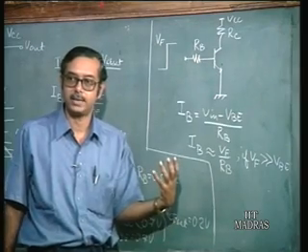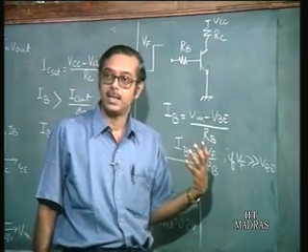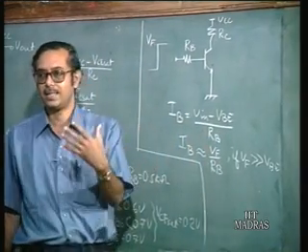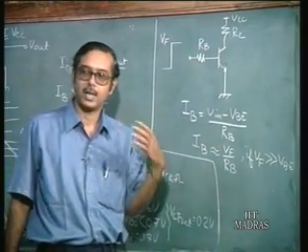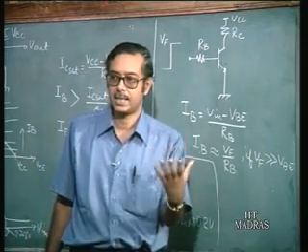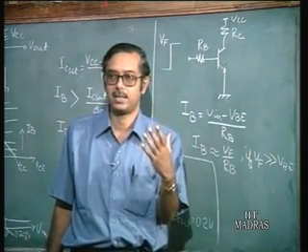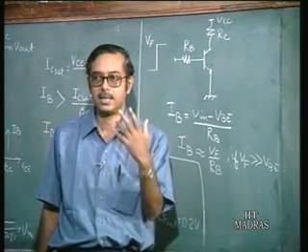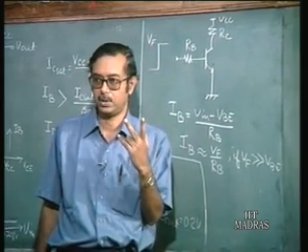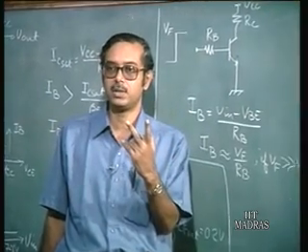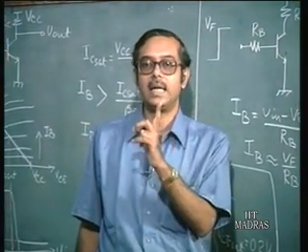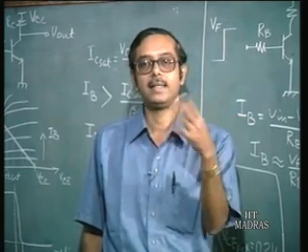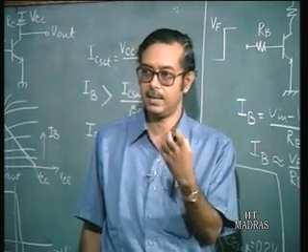So, the relation again is, for that, let us consider a transistor. Let us go back a little bit. We have already discussed the base current of a transistor. In the forward conduction mode, it consists of basically two components, if you remember. One is the injection of carriers from the base to the emitter, and the other is the recombination of charges in the base.